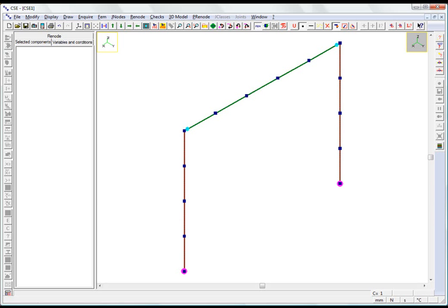In a finite element model or FEM model, the elements are attached to very specific points in space called nodes. The nodes generally have 6 degrees of freedom, free translations and free rotations. On account of the mesh, the nodes in a finite element model do not always represent points where different members are joined. Many nodes in a finite element model do not correspond to nodes where members are actually connected.